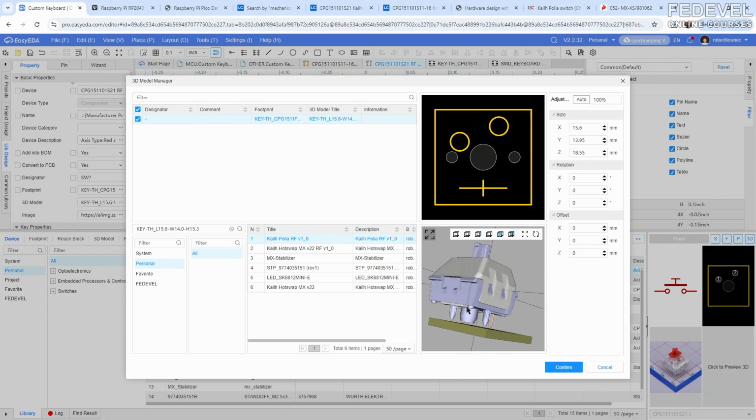Here it is. We need to adjust the position, so I'm going to change this. And double check, okay, there are the pins and there are the legs. We just need to move it a little bit. Put here these numbers. Okay, and you can see the pins go directly into the middle of the holes, and these are the legs, they are going inside, and there is the position for the LED.